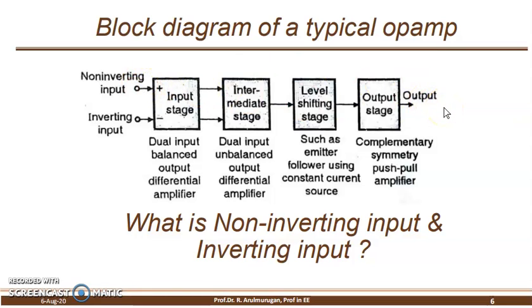Keep this in your mind, it is very important whenever you draw the waveform. How does it happen? Because I connect the source to the V plus, so the value is the same. Plus means plus. I am not talking about the output voltage, I am talking about the phase shift. Is there any phase shift? No phase shift. What about the inverting mode? I give the source to the inverting input: plus 1, minus 1, plus 1, minus 1.